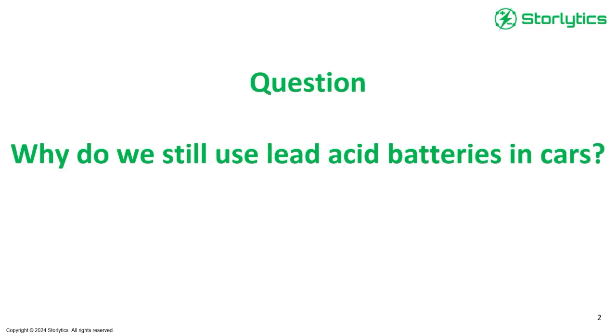That's one factor. Rapid discharge, C-rate, exactly, right? It'd be recycling. Okay, that's probably true as well. But the one I had in mind was C-rate, right? Lead-acid batteries are really, really good at giving a lot of current in a very short period of time. Compare that to lithium today, it's not as good at it. That's why you don't see lithium batteries replacing lead-acid batteries in cars, right?